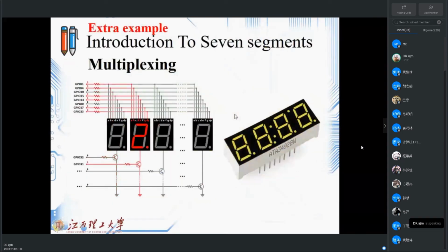See one more example, which I don't want you to do for the task, but I want you to know this: as you see, if I'm going to use the library, I should engage 11 digital pins of my Arduino board. And if you remember, we have 2 pins for serial that we cannot work with. It means that all the digital pins of my Arduino are gone.